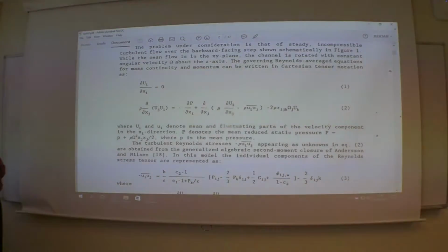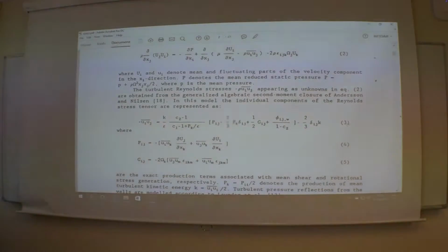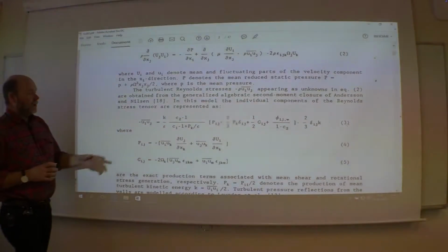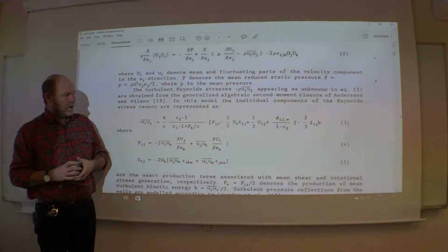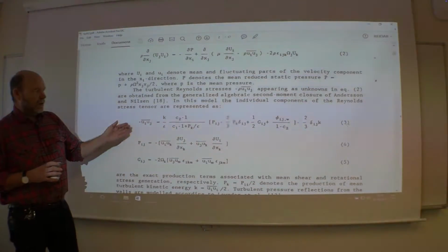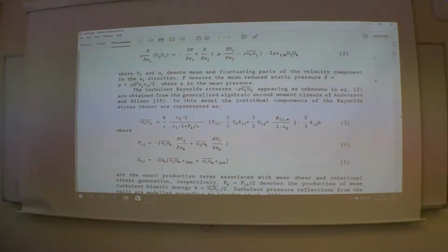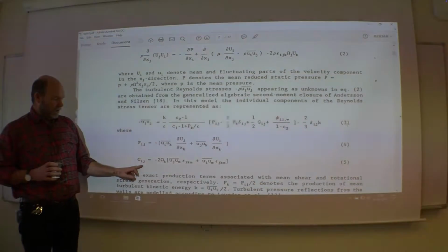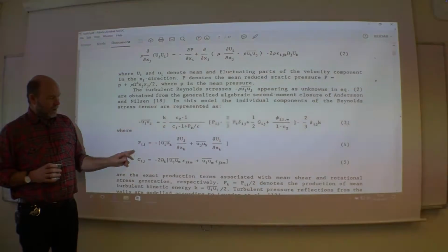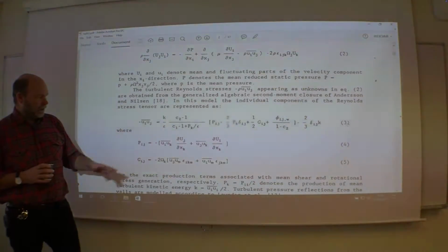So the ASM model here is finding the different Reynolds stresses after you have a solution with K and epsilon. Fairly messy model, but possible. The production term, and also the Coriolis force term, will be okay to handle.